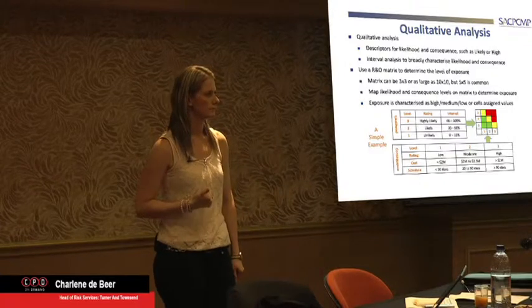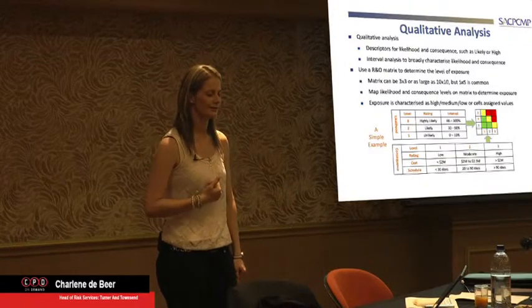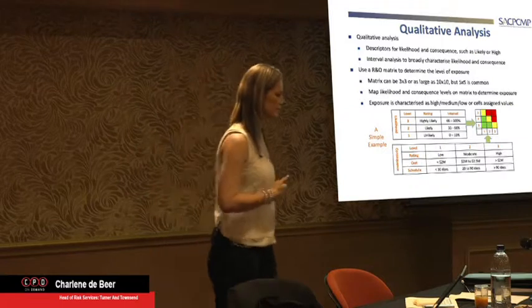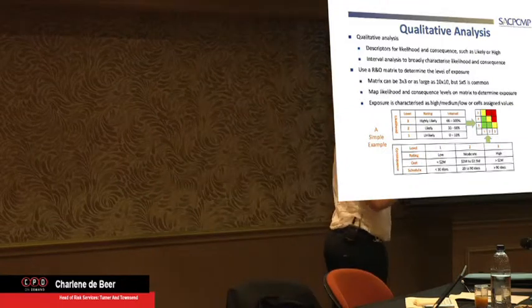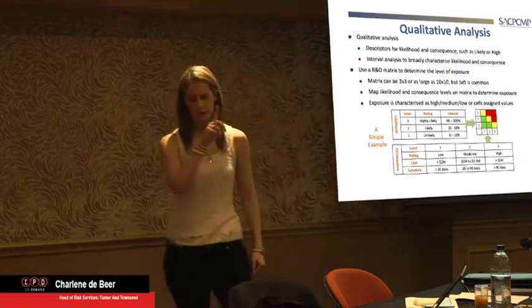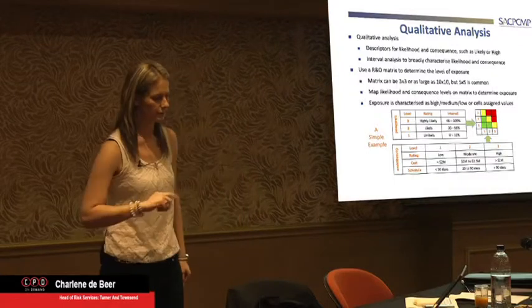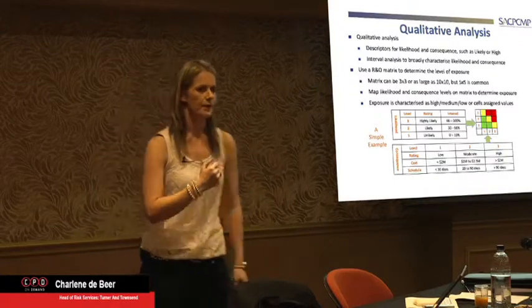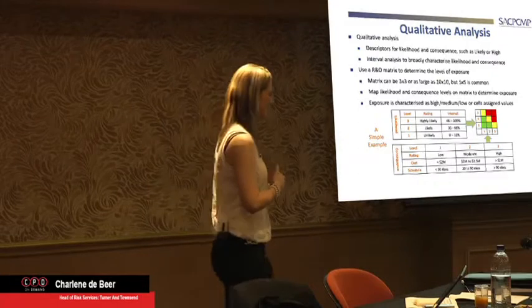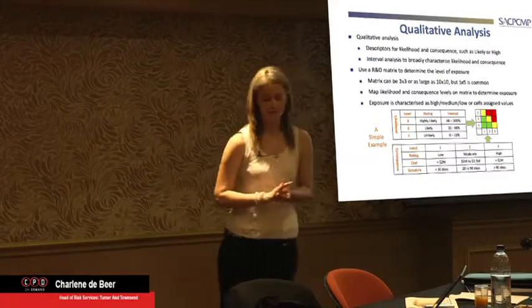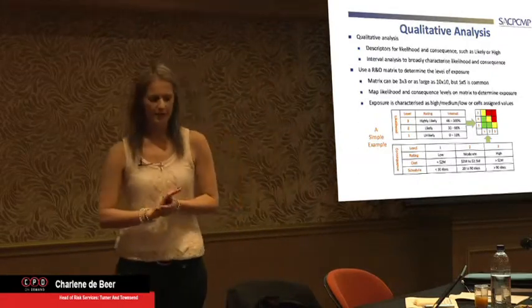Because the more detail you have, the better you can cost it and allow for it in your schedule. And this is why I usually challenge most of the estimators and the planners. An estimator will thumb-suck 10% of contract value. That's his contingency. Very interesting. And they'll build in float. How they establish float is also debatable.